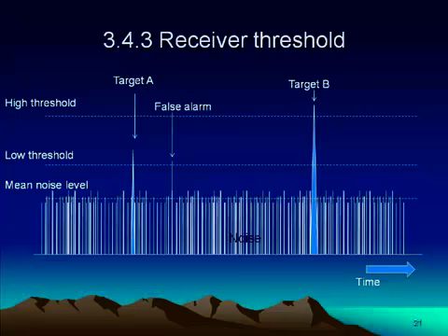But if you want to avoid this, you may jump to the conclusion that you may put a high threshold level. With a high threshold, you may be able to avoid false alarms or the noise itself crossing the threshold limits. But also, the far off targets will not be detected because the echo from these targets will be quite low compared to the threshold, and they will be ignored at the input itself.